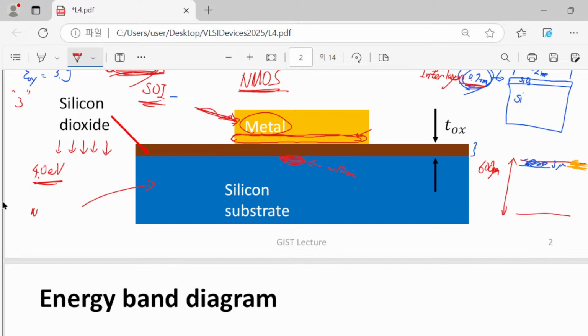For example, in the case of N MOSFET, if you wanted a higher threshold voltage, you introduce more dopants, then you can increase threshold voltage. If you wanted a lower threshold voltage, you reduce the implantation dose, then you can have a lower threshold voltage, so higher performance. That was a previous trick, and we will follow the previous recipe.